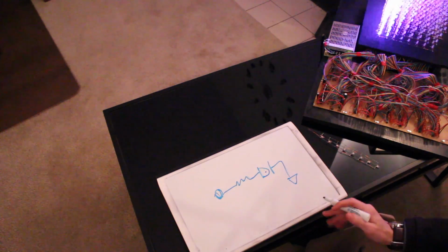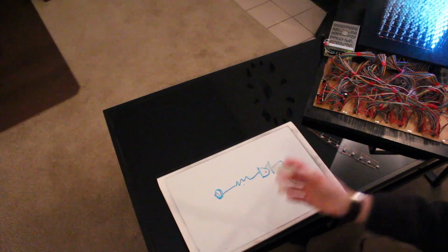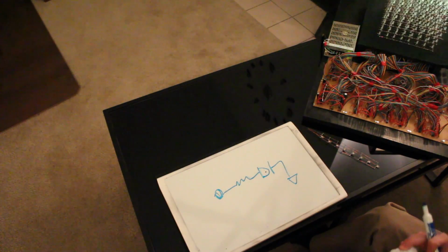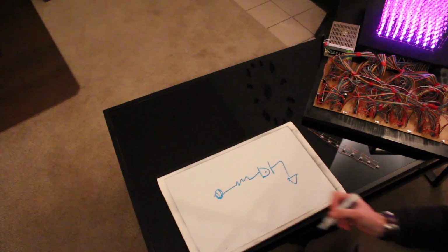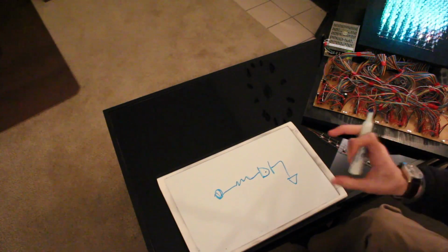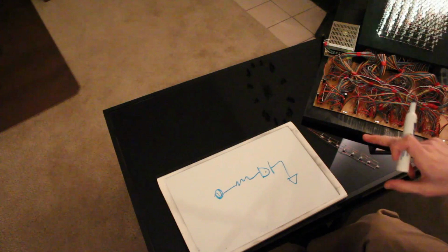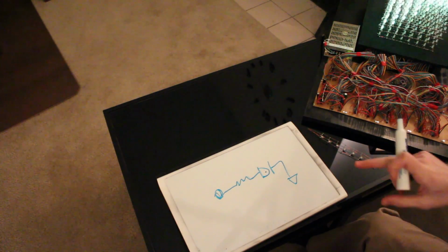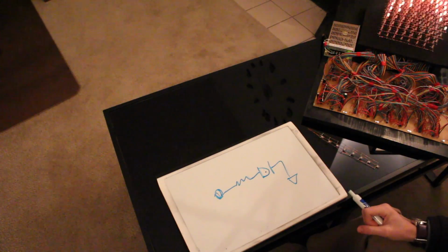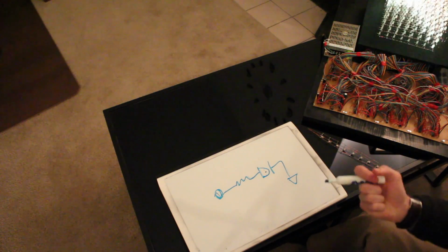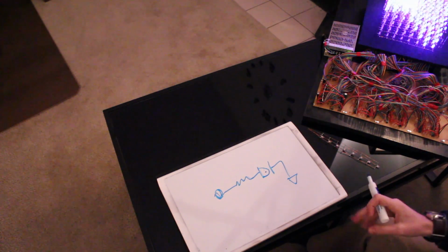To control the brightness of it, you could vary this resistance, but of course that's not possible. So what you do is control it by modulating this pin. And if you hold up that blue board, the Arduino board, you'll notice that some of the pin names have something called PWM next to them, and that's pulse width modulation. And that's actually built into the hardware of the Arduino, so it makes it really easy to control.